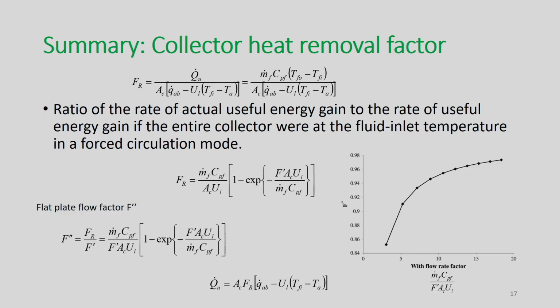So, if we summarize the collector heat removal factor, we have already defined how FR can be calculated, which is the ratio of the rate of actual useful energy gain to the rate of useful energy gain if the entire collector were at the fluid inlet temperature in a forced circulation mode.